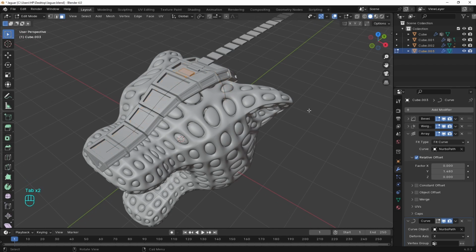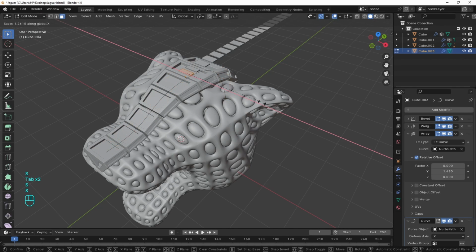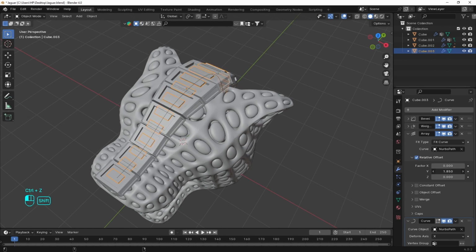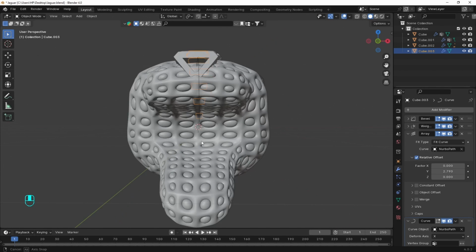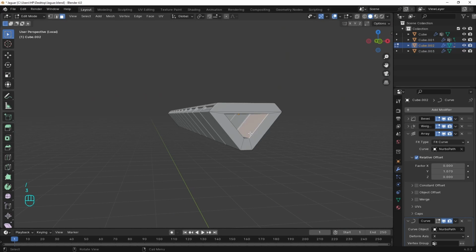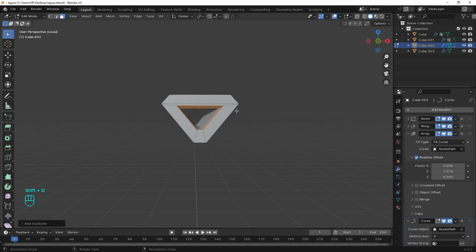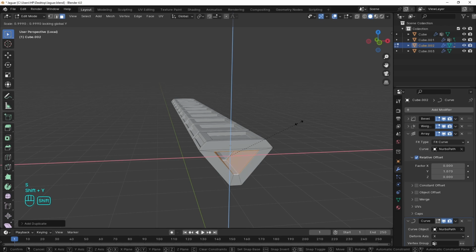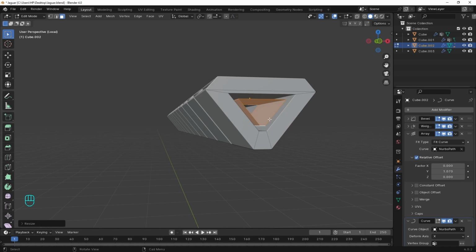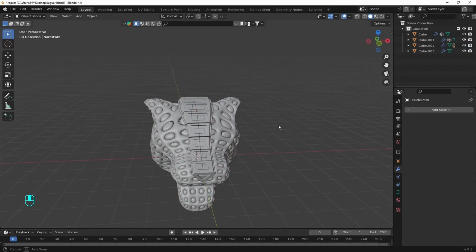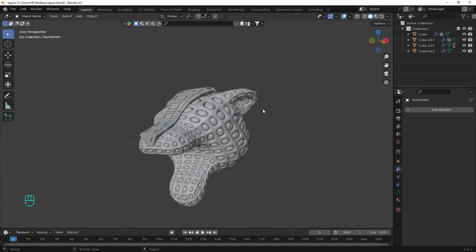The factor depends on the shape size in relation to the origin point, so first get the shape right and adjust the factor after that. Duplicate in these faces, separate the selection, and fill the front and the back face with F. I'll rotate the whole thing to look more aggressive and interesting, if you will.